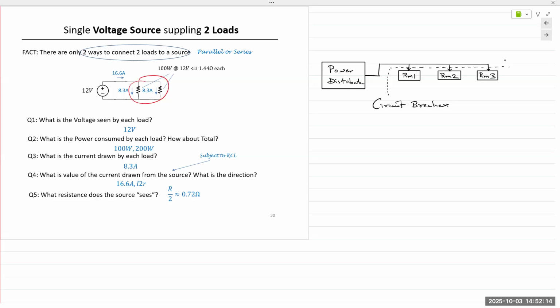When it trips, it activates a switch, and the circuit is broken. Hence, we call that device a circuit breaker. So if you put each individual room on its own circuit breaker, if a fault occurs in one of the lab benches, it trips the circuit breaker for this room, disconnects it from the rest of the electric power lines, and thus the other rooms are not affected.